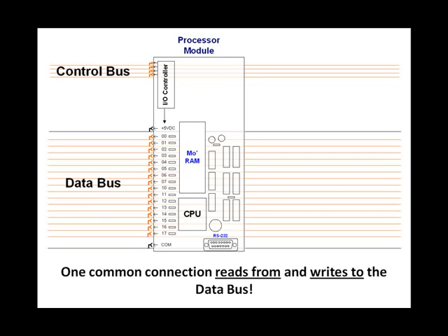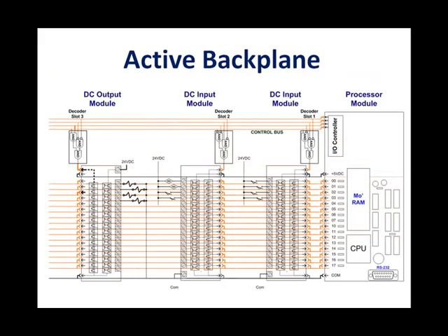What separates the PLC from other industrial controllers is this I/O scheme that allows you to use many I/O cards, inputs and/or outputs, or combinations thereof, and of many voltage interfaces. This literally was the primary differentiator between a single board computer controller and a PLC. The programming language, ladder logic, used to program PLCs, that would be the second item, and we'll cover that in a bit.